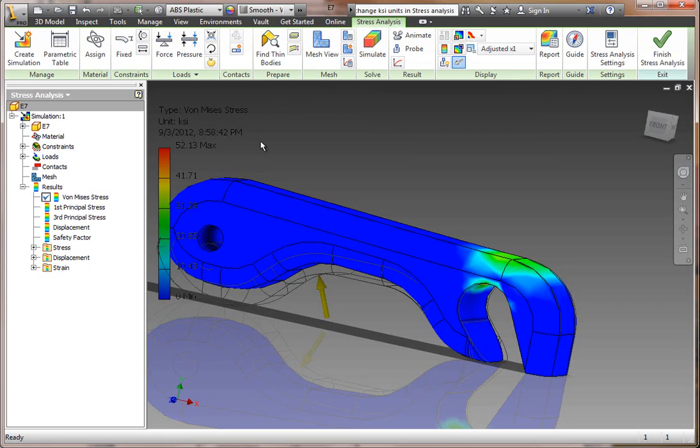Typically that information is found on material data sheets that you could locate online. So for example, ABS plastic, one of the manufacturers is Bayer. That's the same manufacturer as Bayer aspirin, actually. And you could look that up and look up material specifications for the ABS plastic. And there's various types of ABS as well where they mix other materials with it. But you can find out the average strength, or tensile strength, for that as well.